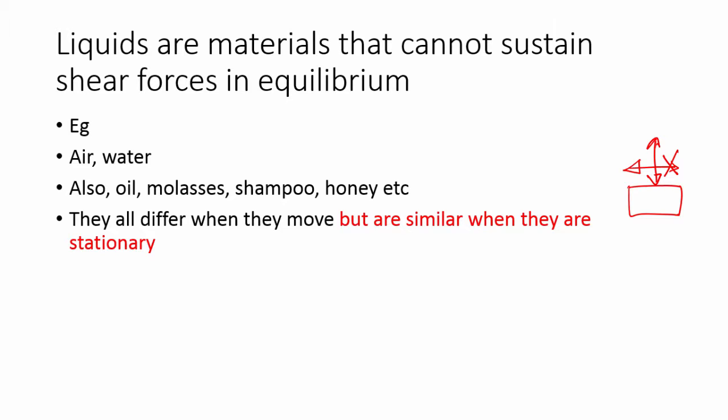One of the ways in which we are going to utilize liquids is that we are going to assume that they are roughly incompressible. It matters because we will distinguish between air and water. Air is compressible, so it will occupy the whole box by expansion or compression. Water may not be able to occupy the whole box, so it has some surface. So this matters because in the cases of liquids which have free surfaces, you know what is meant by a free surface, right? It's not occupying the whole box, but there's some gap. In a free surface, it turns out that gravity becomes a very important aspect. That is the very key idea.